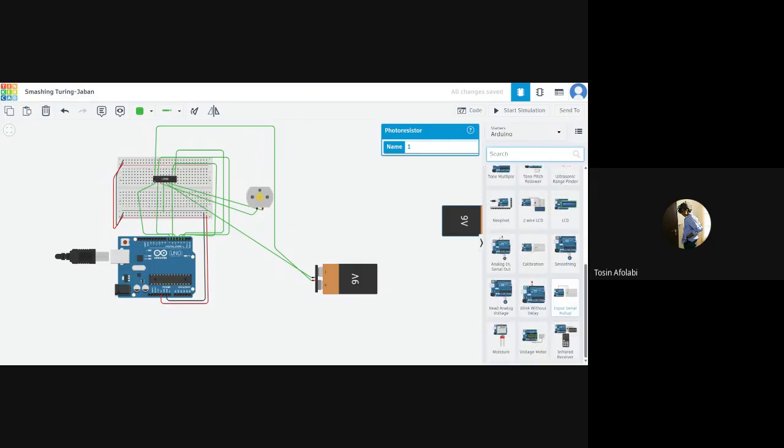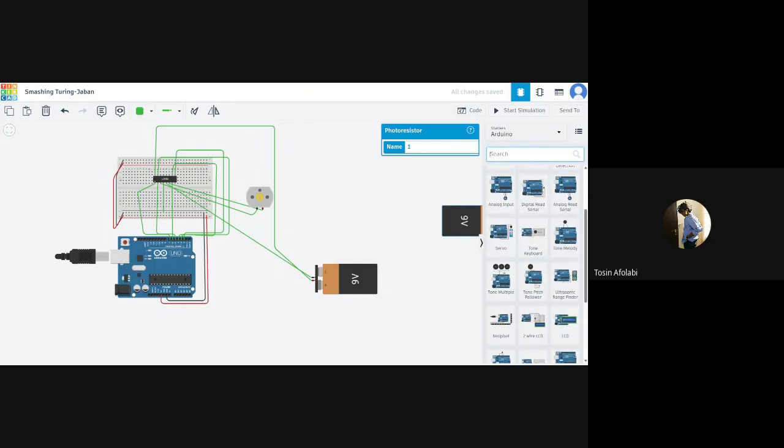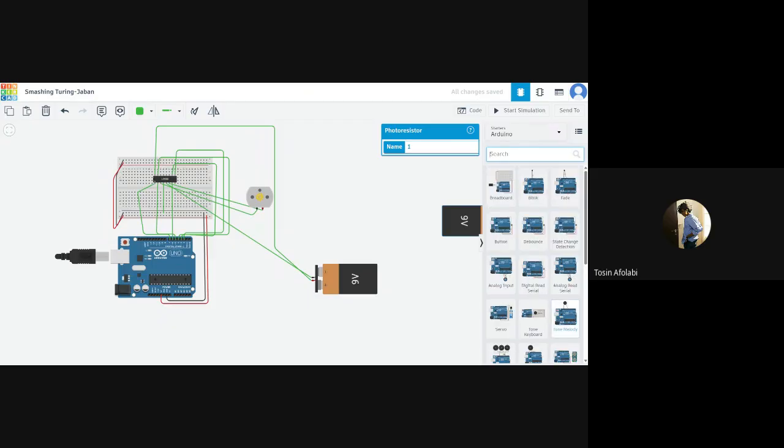I'm very sorry that this is looking confusing. It's actually what I go through because I've never actually used Tinkercad before having to teach you guys. It seems like the H bridge I'm actually looking for, the L298N, is not available. With the best of my knowledge, all my connections are right, and it's overloading our Arduino pin.